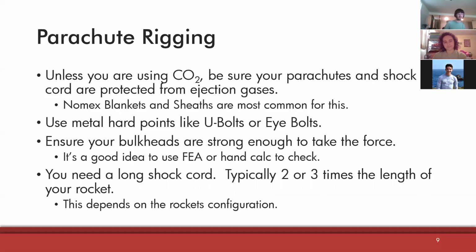Another really important thing, use metal hardpoints like U-bolts or I-bolts to secure your recovery rigging. It's important that things aren't being ripped off. And that goes hand in hand with making sure bulkheads are actually able to withstand the recovery forces. It's always a good idea to double check using some FEA, if you know that, or just plain structures math from whatever your last structures course was. It's a very practical application.